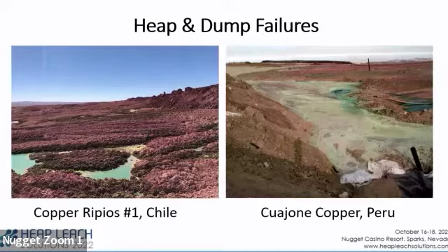Now, this is a copper oxide because oxides consume a lot of acid. They use interlift liners. So the liquefaction, which is pretty much a full flow side liquefaction, was only the top lift because underneath that interlift liner, it was unsaturated. So this was kind of an inconsequential failure, a little bit of operational disruption.